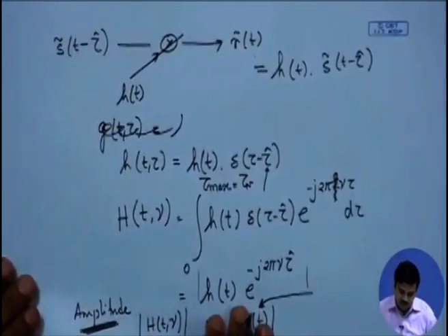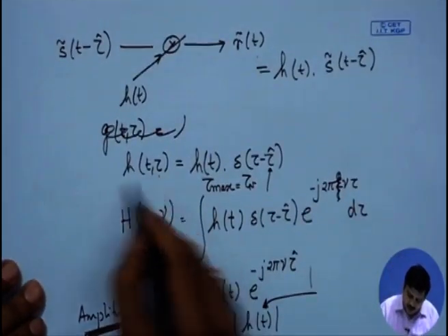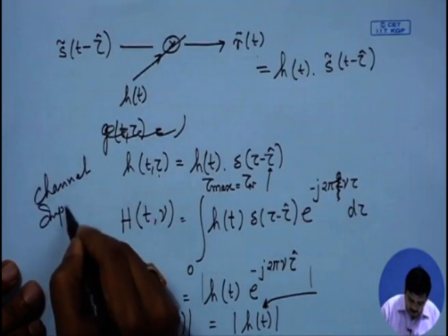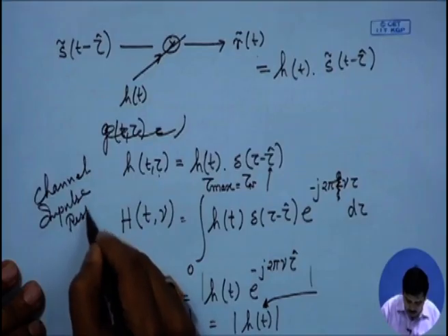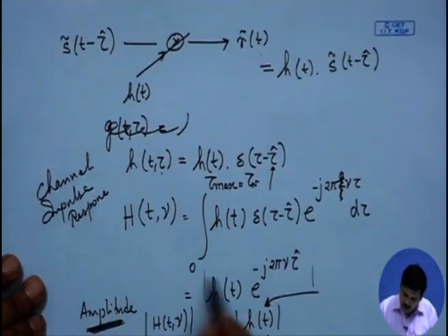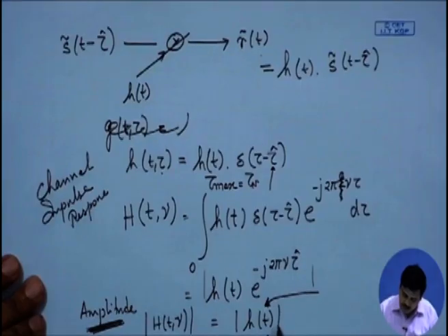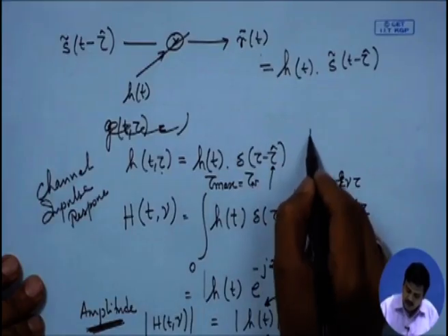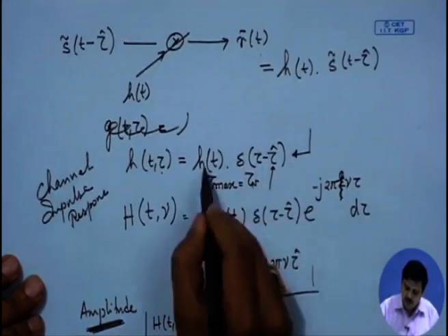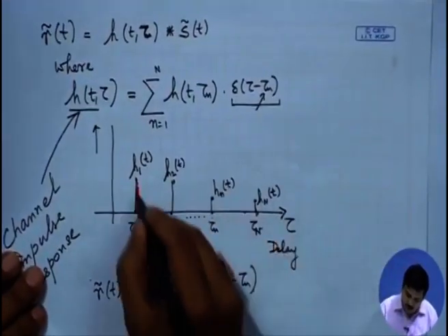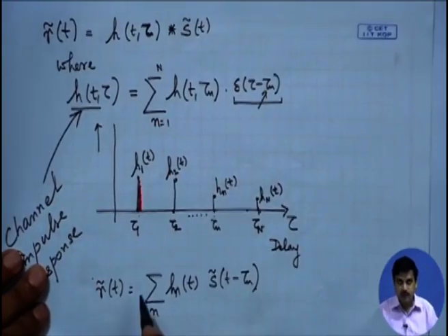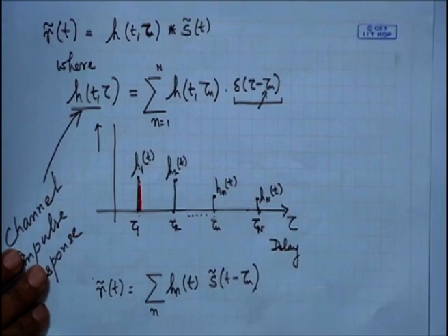As we have clearly seen, if we take the Fourier transform of this channel impulse response, we get a situation which is independent of frequency, if we take the amplitude of it. The reason being the channel impulse response is simply one delta function which is scaled by a value, or in other words, it is just one impulse. And if you remember, the Fourier transform of an impulse is flat across the entire range of frequencies.